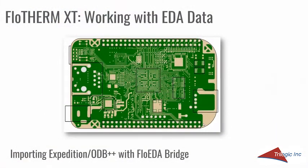The last example we will look at is based on the ODB++ format. This format includes geometric information of the nets. In this context, a net is the copper traces and vias that carry a specific electrical signal or current, but may also have a significant effect on the heat transfer. Historically, it has been time-consuming and challenging to build a thermal model with this much detail. With FloTHERM XT, we will see that it is a process that doesn't require advanced CAD skills.